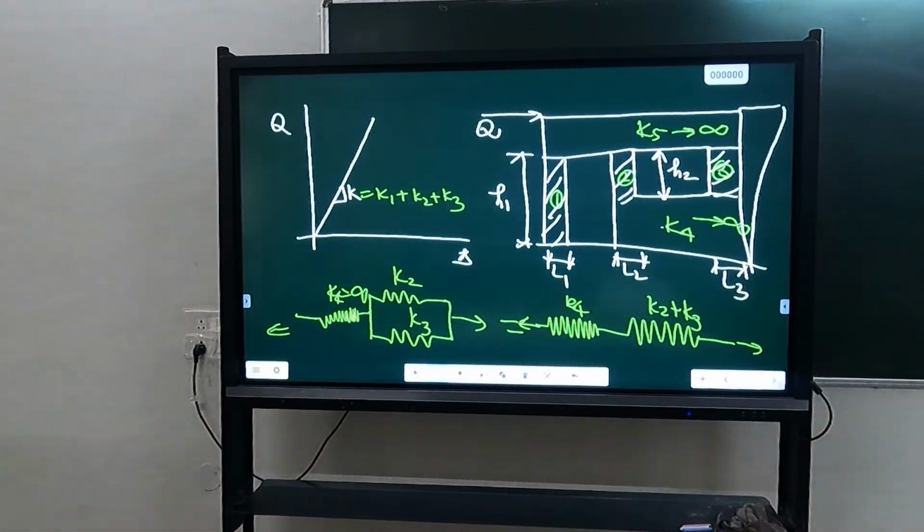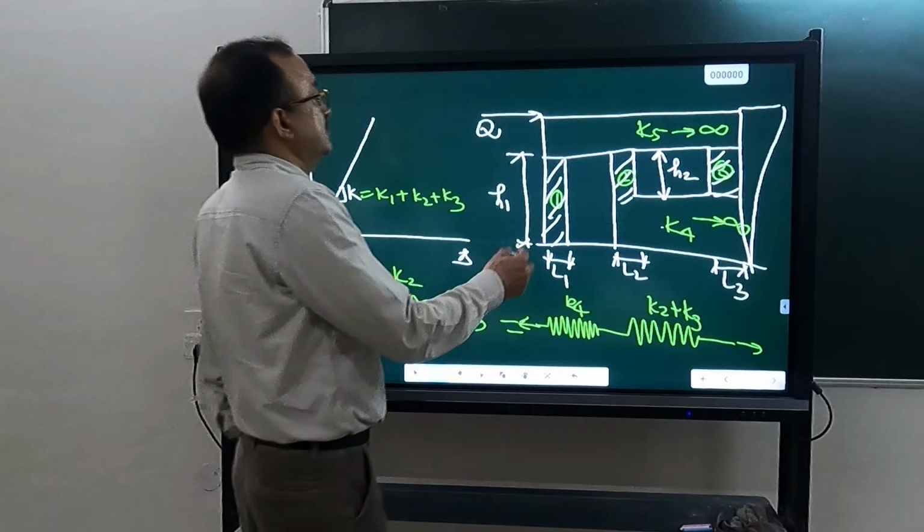You have seen, in fact I have also shown you photographs of failure of masonry buildings. You might have seen a lot of photographs in which the masonry walls have failed. So what are the different modes of failure? Diagonal tension. What is that? How will it look? If a building is failing in diagonal tension, how will it look? Can you plot? The cracks will start from the corners of the walls and in between the middle.